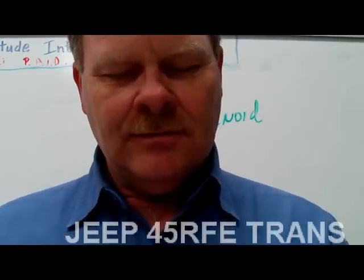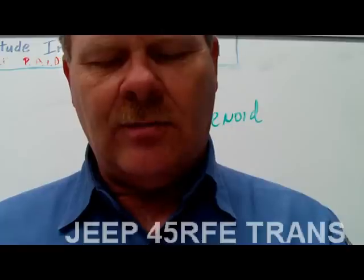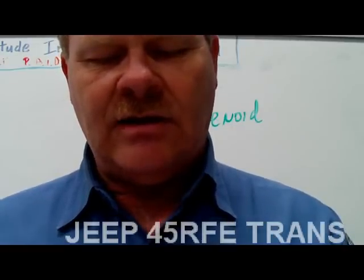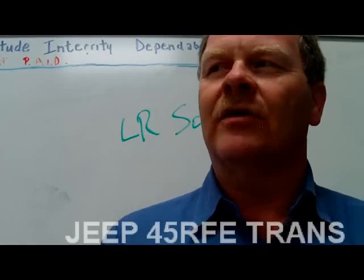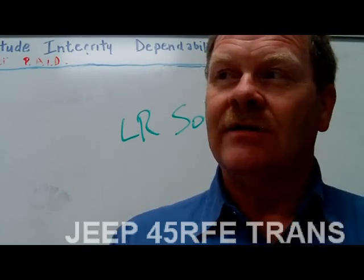He dropped the ball. The other one is the transmission fluid temperature, and that's monitored by the PCM. Based on the transmission fluid temperature, the PCM may energize the vehicle's electric coolant fan. Listen to that. Did you know this? If the transmission fluid gets too hot, the PCM may turn on the coolant fan, even if the engine coolant is not all that hot.